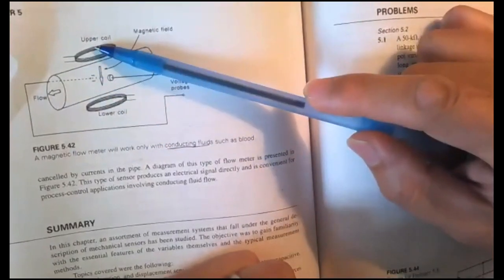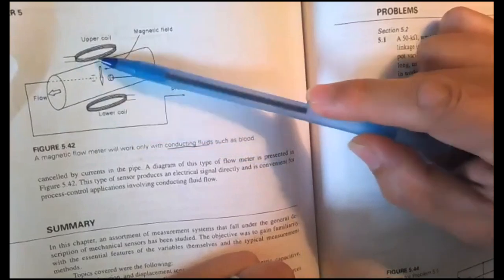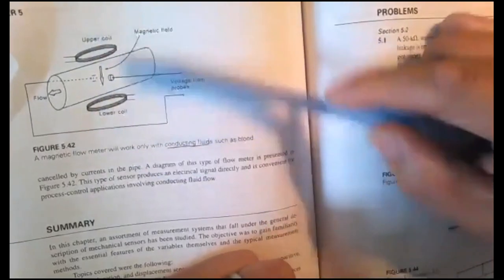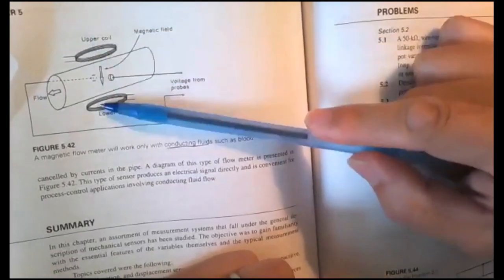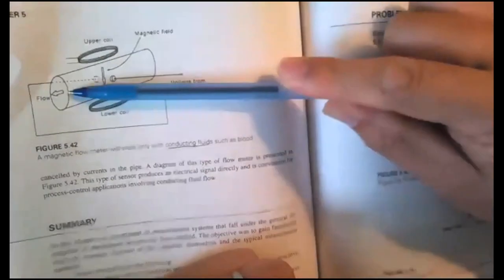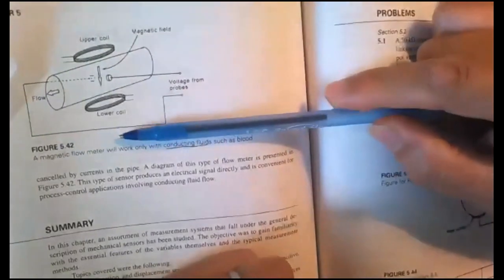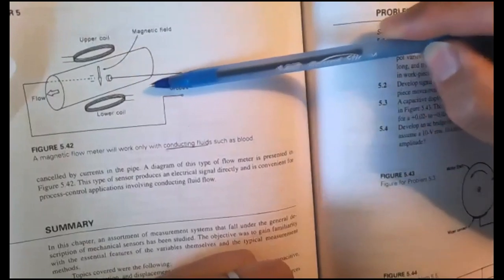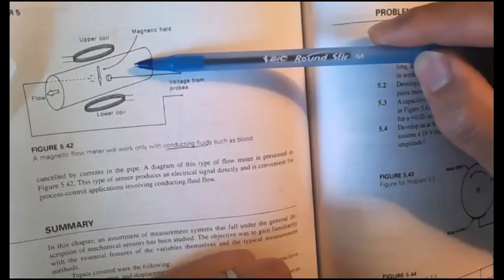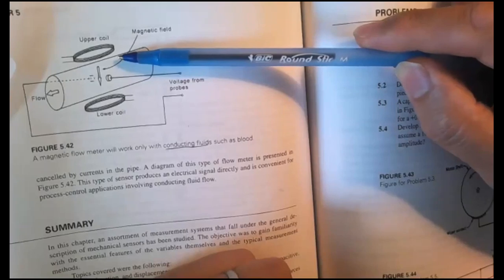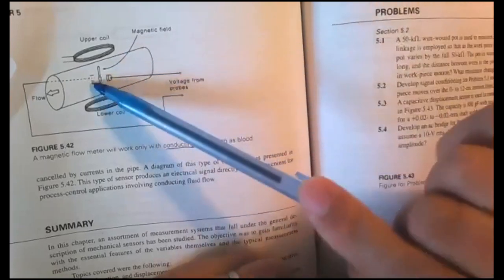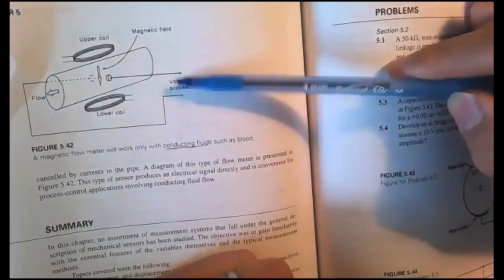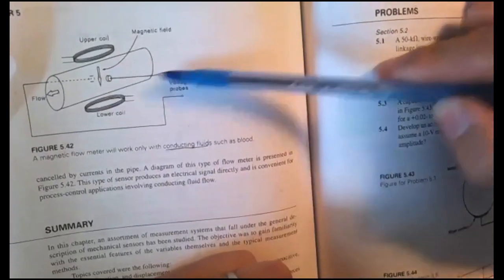The sensor works by having a magnetic field. So we are creating a magnetic field. What happens if you have a magnetic field, then you're pumping dirty water through the pipe? When you have a magnetic field, and you're pumping dirty water through the pipe, the dirty water becomes a generator. It will generate electrical power. Not very much, milliwatts, very weak electric voltage.